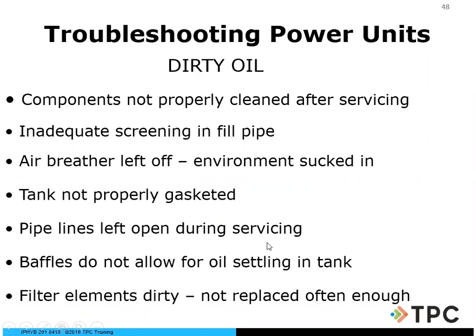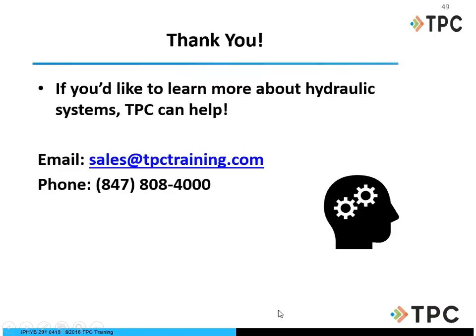So what I did, I covered it up with plastic, made sure it's all nice and clean, or used caps, so nothing crawls in there and gets into my system. And then I put it back together. Filter elements dirty but not replaced often enough. So these are critical things. All right, so this brings us up to this point here.